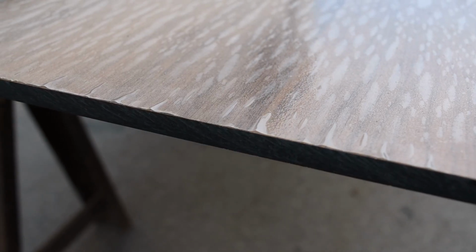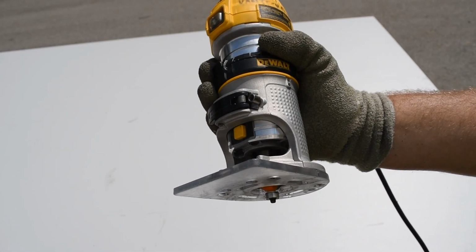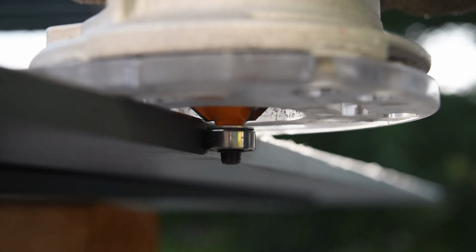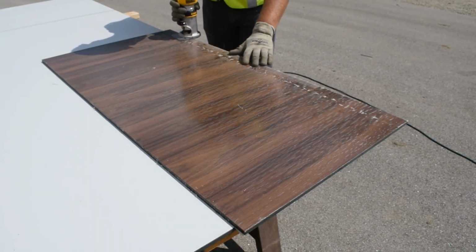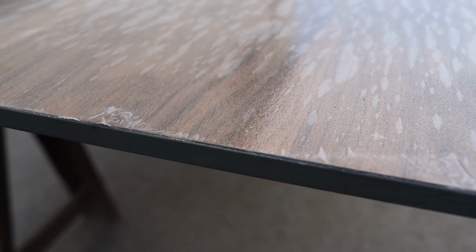This is what a cut edge will look like. The final step after any cutting process is chamfering the cut edges. To do this, you'll need a hand router and the correct chamfer bit. Use a factory manufactured edge to set the depth of the router. Once set up, chamfer all field cut edges. This is what a chamfer edge will look like.